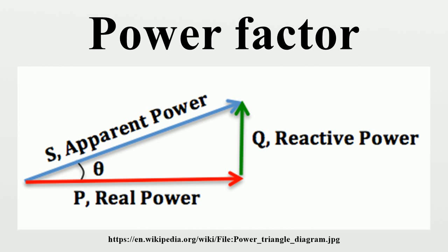Linear circuits. In a purely resistive AC circuit, voltage and current waveforms are in step, changing polarity at the same instant in each cycle. All the power entering the load is consumed. Where reactive loads are present, such as with capacitors or inductors, energy storage in the loads results in a phase difference between the current and voltage waveforms. During each cycle of the AC voltage, extra energy, in addition to any energy consumed in the load, is temporarily stored in the load in electric or magnetic fields, and then returned to the power grid a fraction of the period later.